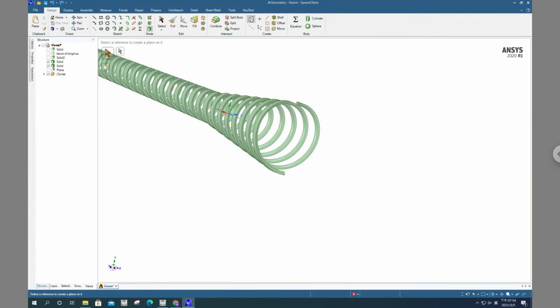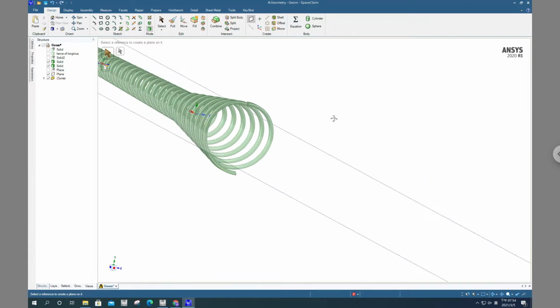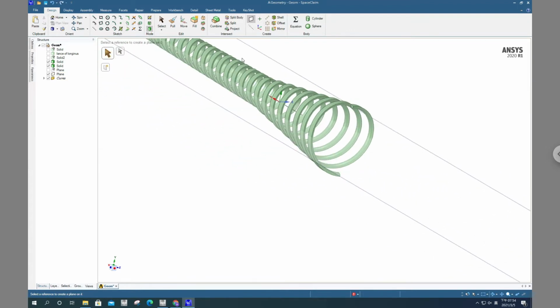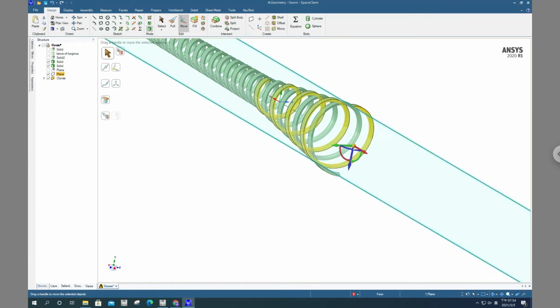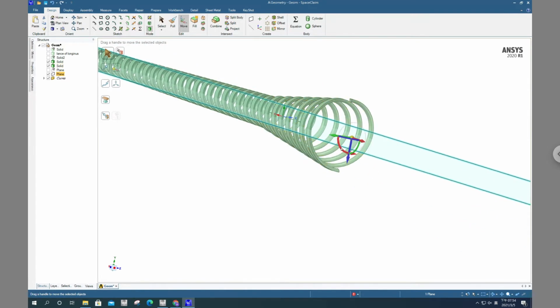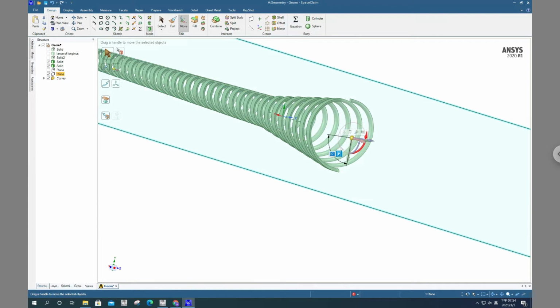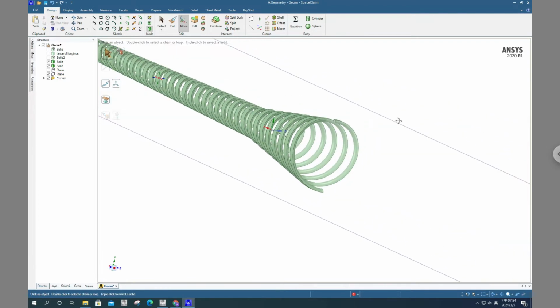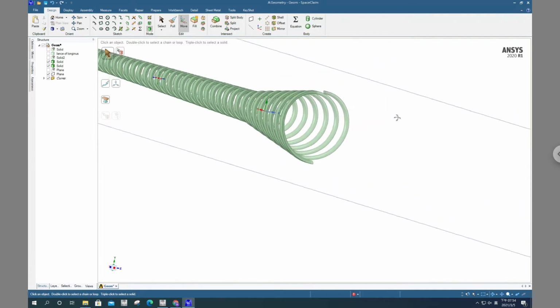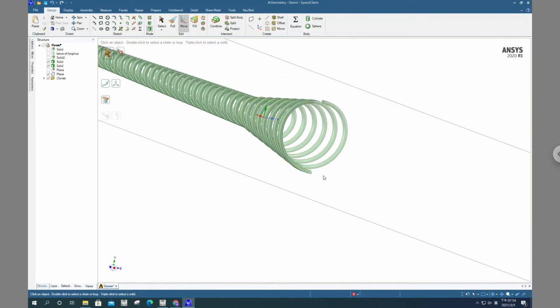So you first click on plane, then click the axis that we created previously, and then we click on move, and we see a move tool that sits on the plane that we created. So we double click the red revolve axis, and we spin it 90 degrees. So we see that the plane now intersects these two points.